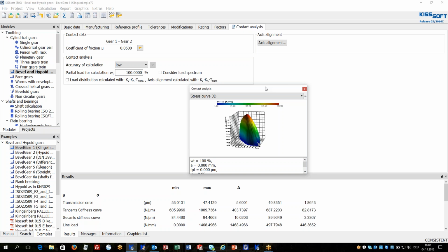Now I will continue with 3D models and processes. For manufacturing, typically Gleason and Klingelberg machine equipment is used for a mid-size of batch or a big size of batches. So for high volumes, definitely these machines are typically applied. For small batches or maybe spare parts manufacturing, 5-axis milling is established as well, as it is much more flexible.